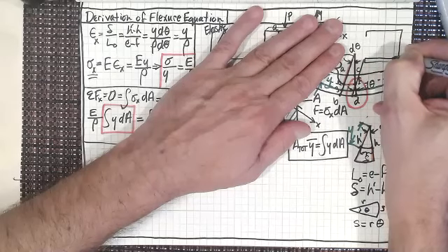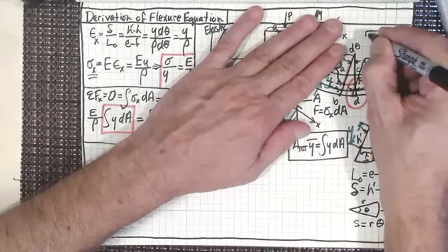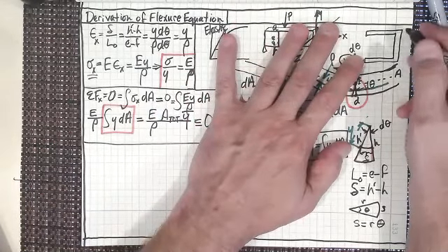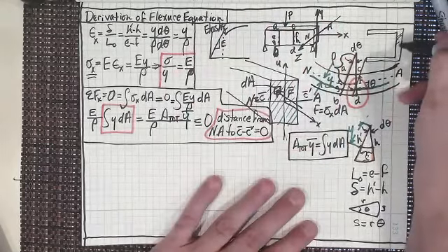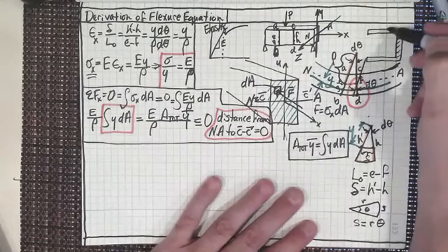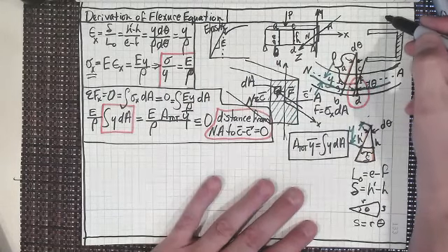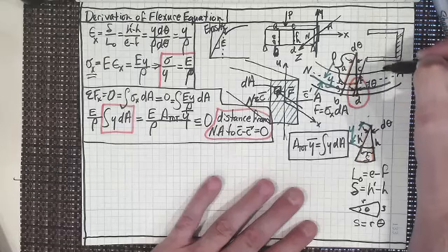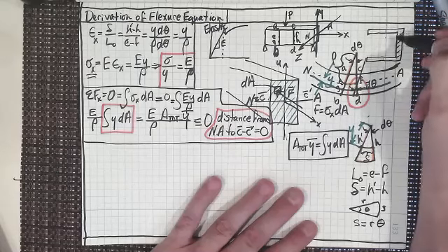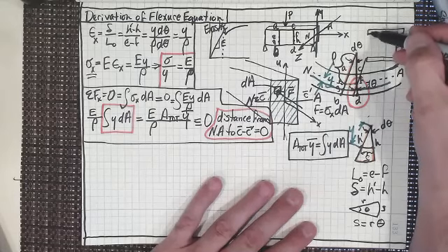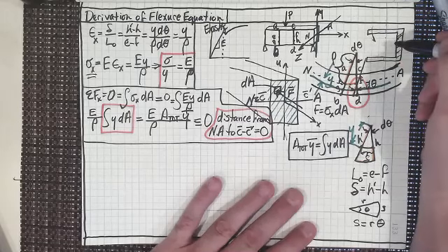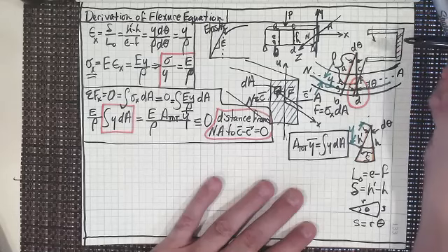The cross section of a beam that looked like this, that only had one side that was supported, right? And then you're putting weight on top of this, but I only have one side here that can sort of do that. Now where's my y-axis? My y-axis would be right down through the center here. But as this thing is loaded up, since I only have a support on this side, don't you think that this would tend to start to buckle? That this would start to have rotations down here, right? That this flange here? That's right.